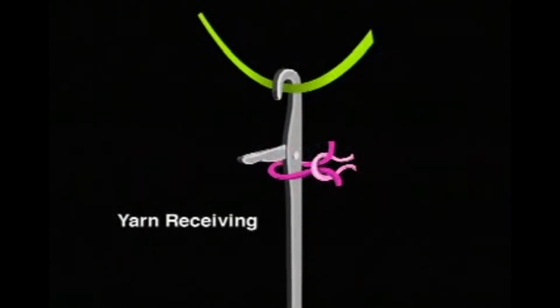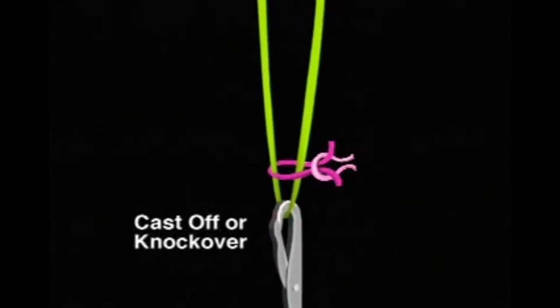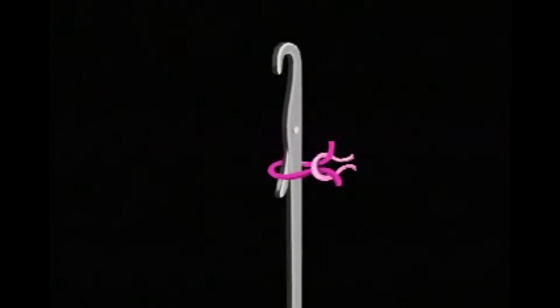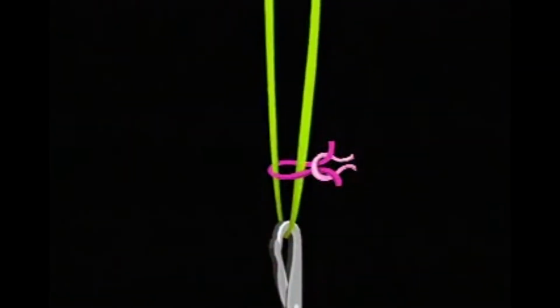As the needle moves down, it receives the new yarn to begin forming a new stitch. The latch is knocked over by the old loop, and this old loop is cast off. The needle moves further down to fully form and complete the new stitch. The amount of yarn used to form a new stitch determines the stitch length. This is important because stitch length affects the weight, width, and aesthetics of the fabric.